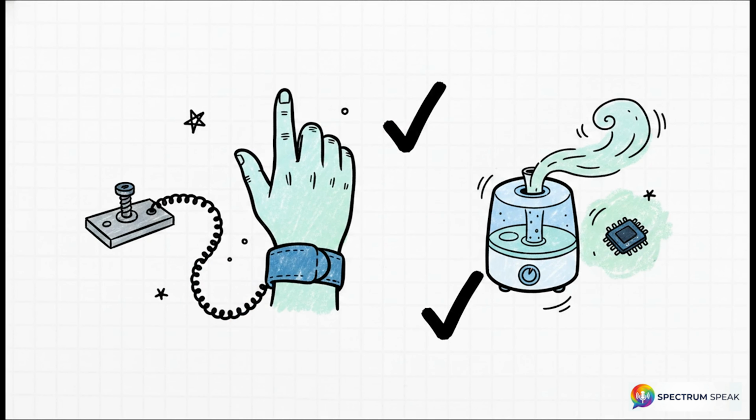Here are your absolute do's for your workstation. First, treat everything as static sensitive, period. Second, always touch a common ground point before handling your assembly. Third, wear that grounded wrist strap. And fourth, this one gets overlooked all the time. Keep your relative humidity at 40% or greater. Why? Because moisture in the air creates a microscopic conductive film on surfaces that naturally bleeds away static charges. Dry air is a harsh insulator. Humid air is a gentle pressure relief valve.